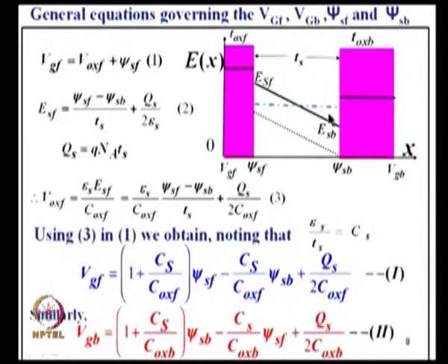It is the general case. We already discussed this in the previous slides. So, what is electric field here? I have arbitrarily drawn the electric field like that, but how much the slope is depends upon the doping. As you start depleting, you can see the slope depends upon doping. If it is very lightly doped, it will be flat. If it is very highly doped, it is going like that. So, I have drawn this diagram here to calculate what is the gate voltage applied for this situation. General case.